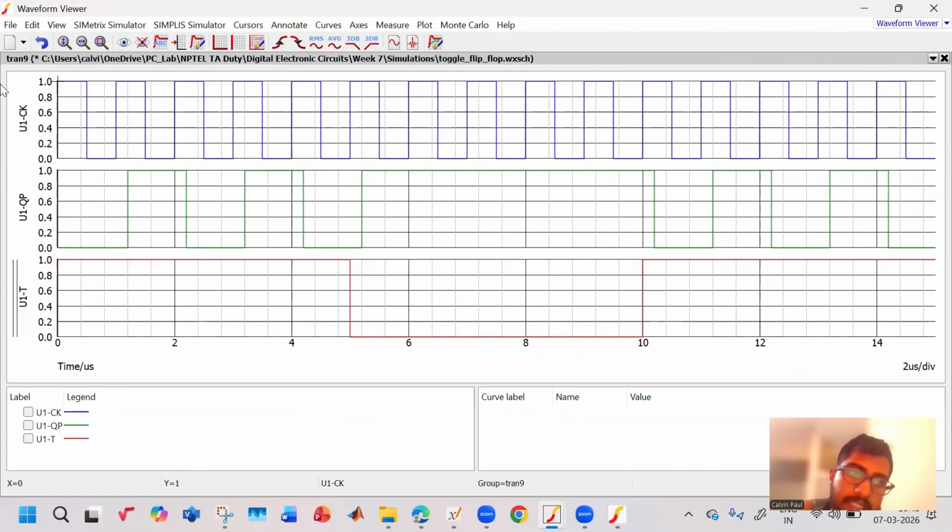Since it's a flip flop, you need to have a high frequency clock. So you have a high frequency clock coming, and then your T is 1 over here. When it rises, after a delay, it is toggling. Then again, after the rising edge, after again a delay, it is falling. Then another clock comes and again T is 1, so it toggles. Another positive clock edge comes, again it toggles. After a delay, the delay is always there.